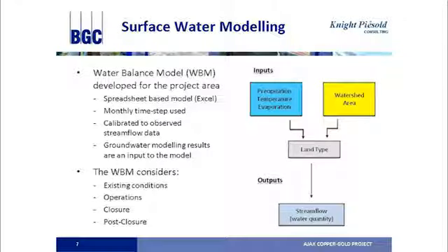I have observed stream flow data, and I set up my model, and I calibrate so that I'm providing a good representation of both the seasonal fluctuations in stream flow, but also annually, year to year. And what I do as inputs to the model, I have precipitation as an input. Temperature is an important input because I have to know when snowmelt is occurring and whether the precipitation is falling as rain or snow. And also evaporation is an important input because, as I said, in this environment, you lose a lot of the rainfall, a lot of the snowmelt to evapotranspiration.